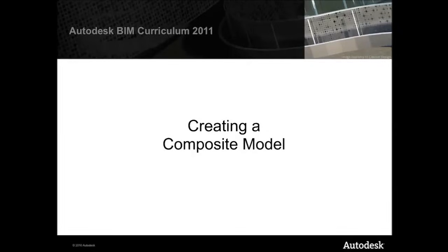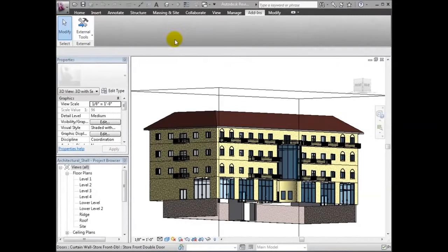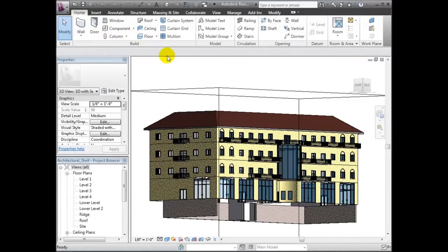The first step to producing our composite model is to export the individual model files into file types supported by the Composite Model viewing and analysis software, in our case, Navisworks Manage. Let's step through the simple steps for exporting files from Revit environments into common file types such as CAD DWGs, IFCs, and native NWC files. We'll start with an NWC.